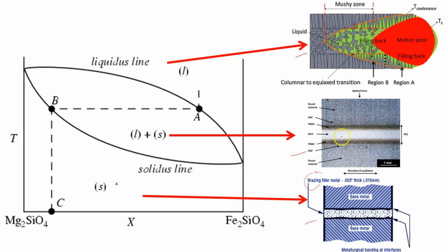Here you're only brought up to the recrystallization state, what also gets called the mushy zone. Sometimes it's called the forging temperature, and this is where you recrystallize your material, and the grain growth causes the bond. And then you're in the solid state level. The base metal never goes beyond the solidus point and solidus line, and the molten metal is the filler material, which fills in the clearance. So let's go into a little more detail on the three of these.